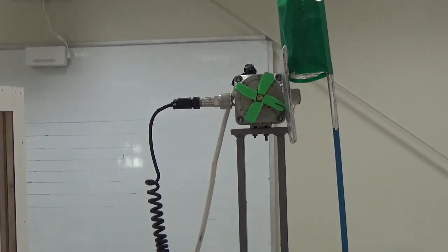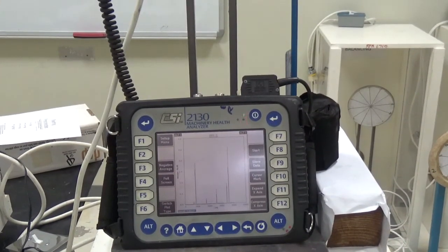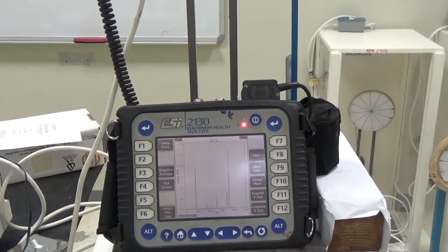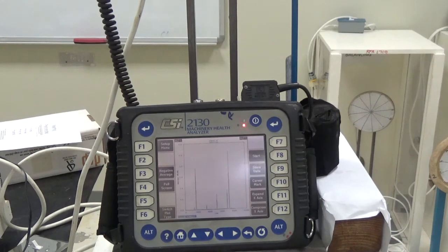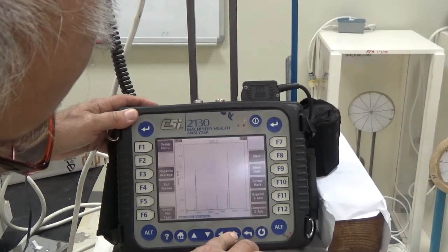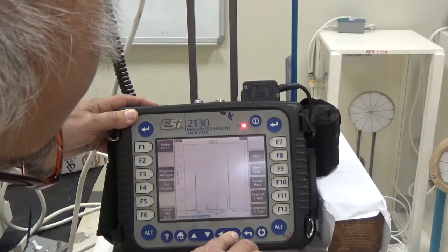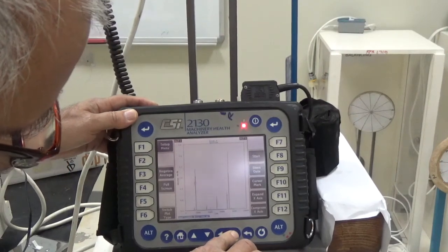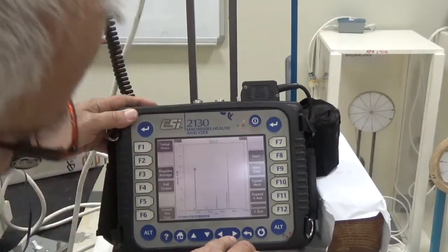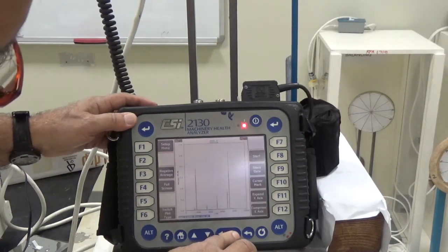So I will stop this one and I will see what is the frequency at blade pass frequency, what is the frequency in the spectrum, and what is the amplitude also. So I will see it. Okay, I will move this one. Okay, so this is the one which tells me about how much is the unbalance, because this frequency is equal to RPM. RPM is 1721. Okay, let's go forward.